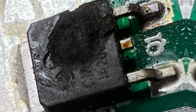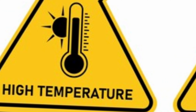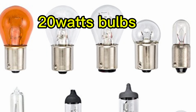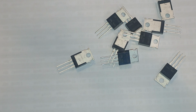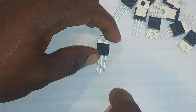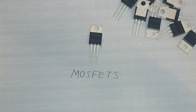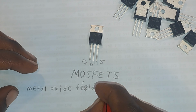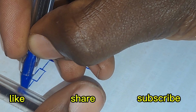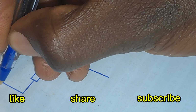One common disadvantage of BJT transistors is that they cannot handle higher loads. So in order to handle big loads, like 20 watt loads, we can use a MOSFET. A MOSFET looks kind of like a BJT, but it is somewhat different, especially in its structure. A MOSFET is called a metal oxide semiconductor field effect transistor. Therefore, it is also under the transistor family.